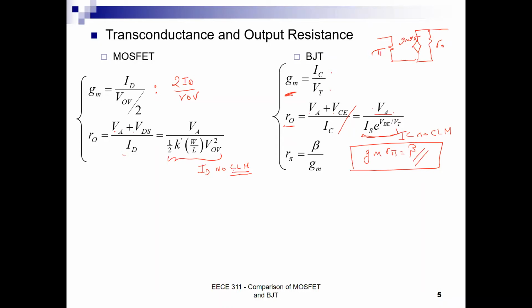Great. Now, there is an alternate model, which is the T model, but it will matter to us only when we study specific circuits where there is, for example, common source with source resistance. When we need it, we will tell you when we are going to use it.